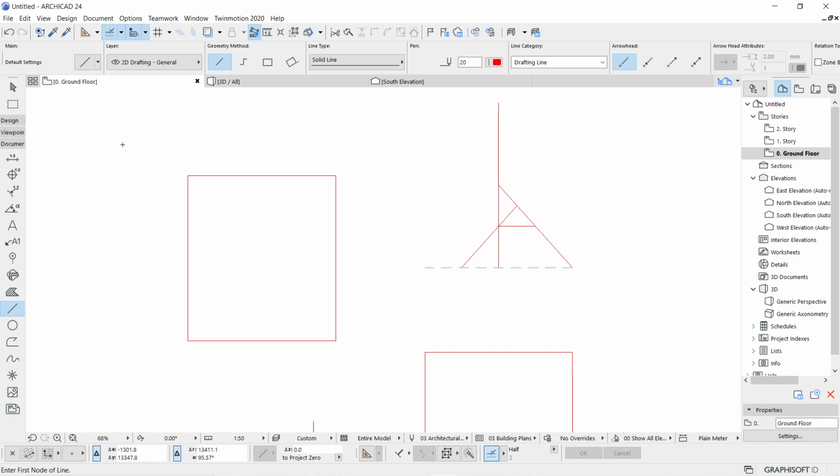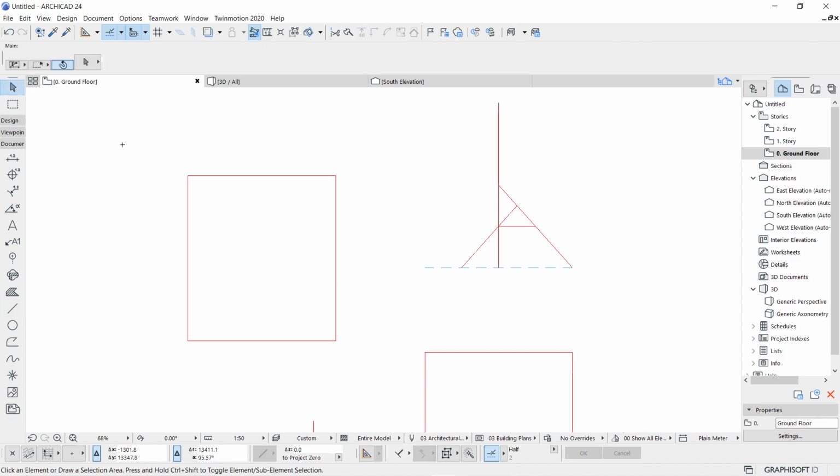If you use escape one more time, then you will return to the arrow tool. So remember this hierarchy. A single escape after selecting the object takes you into the draw mode for that tool, or the object which you were editing. If you hit the escape key one more time, then you will go back to the arrow tool.